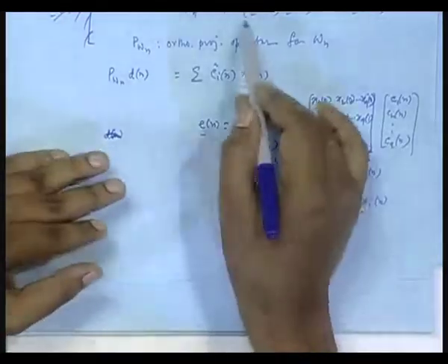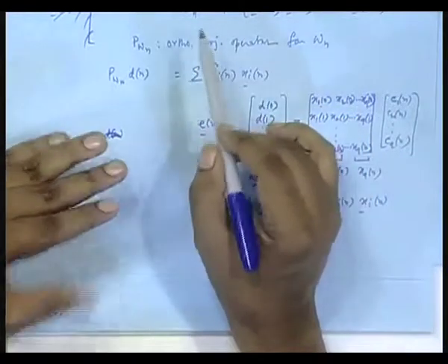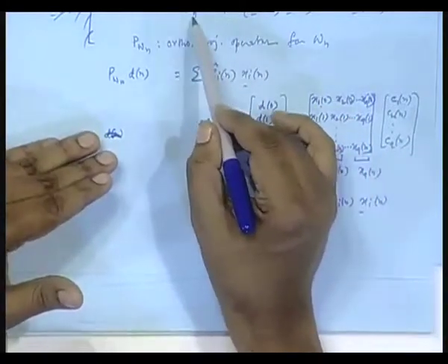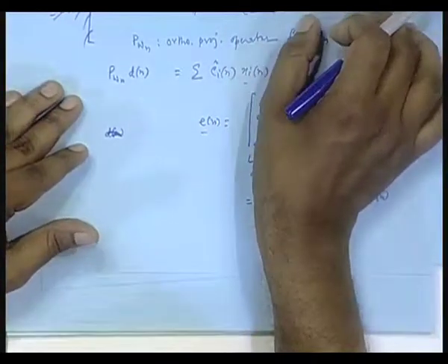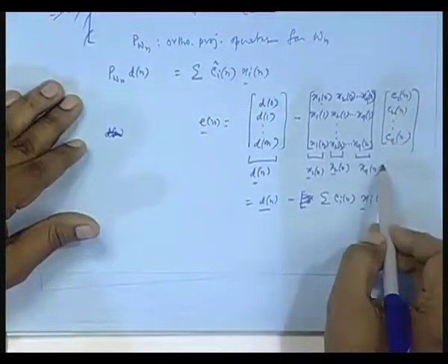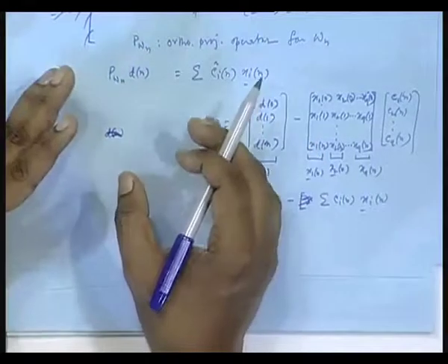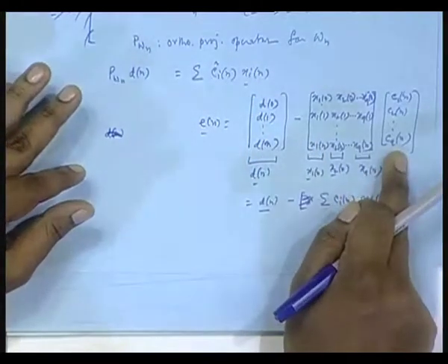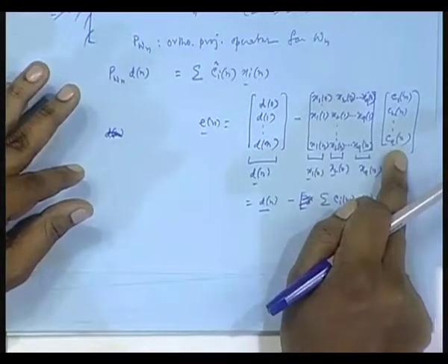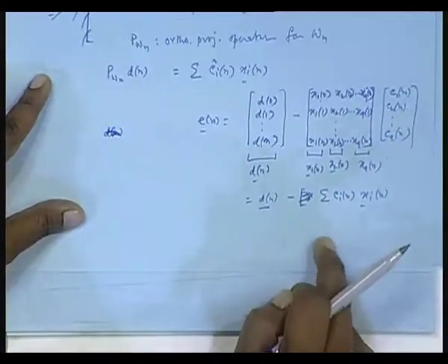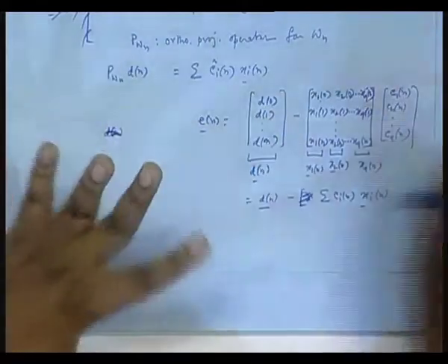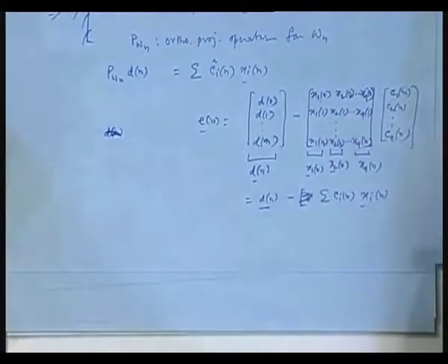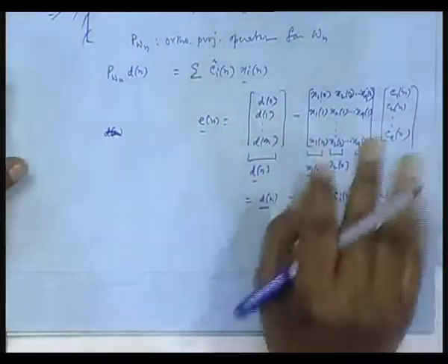Projecting dn orthogonally on the space Wn, the projection will be the best linear combination of these column vectors. Those are the coefficients. This resulting error vector norm square will be minimized because of these. So, what are these coefficients here? Let us find out. We know in the case of the optimal filter, R inverse P and all, but that entire business is out of the purview, no E operator anywhere. But you can carry out a similar treatment.